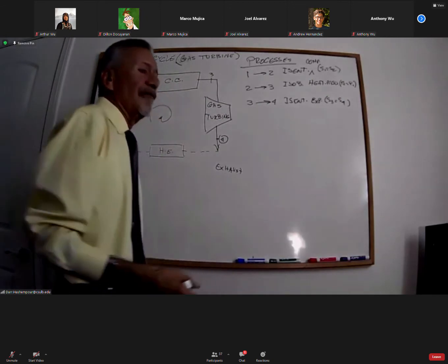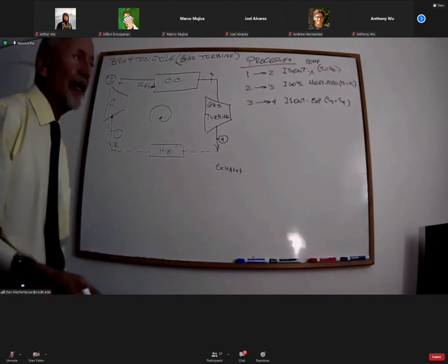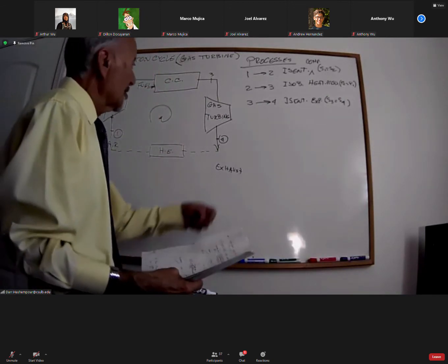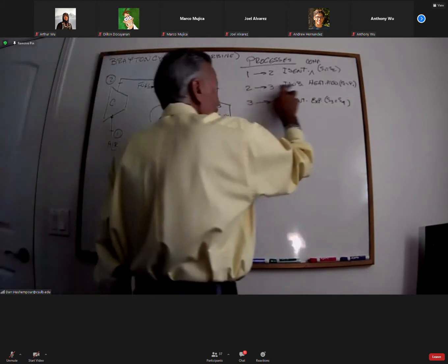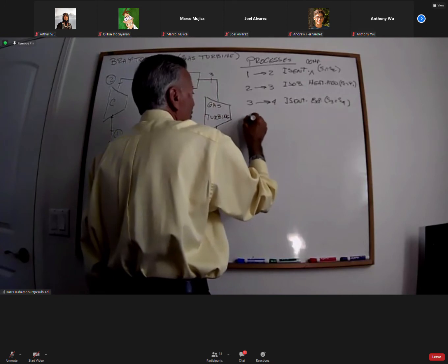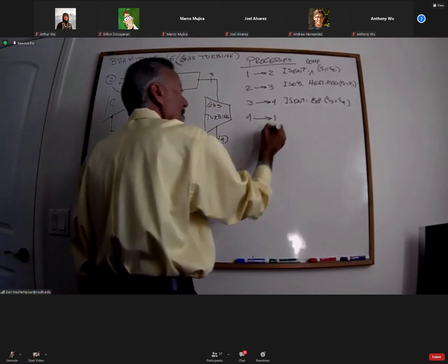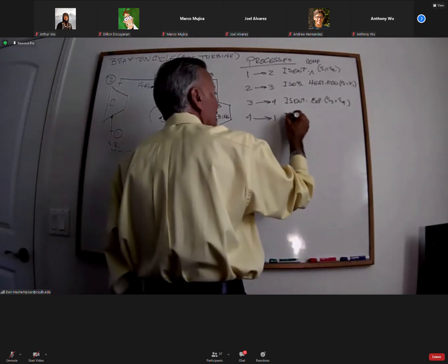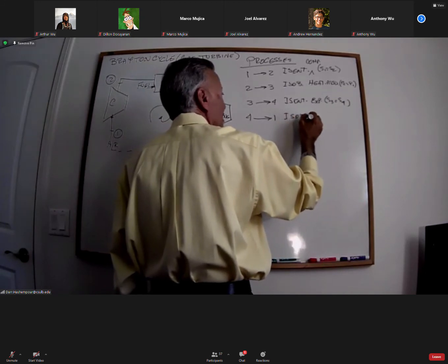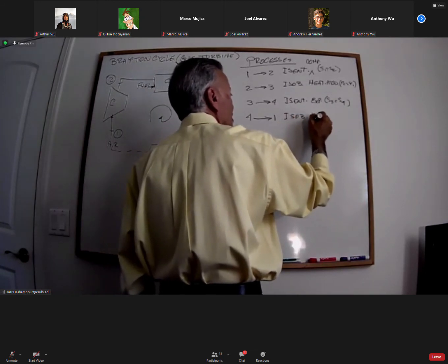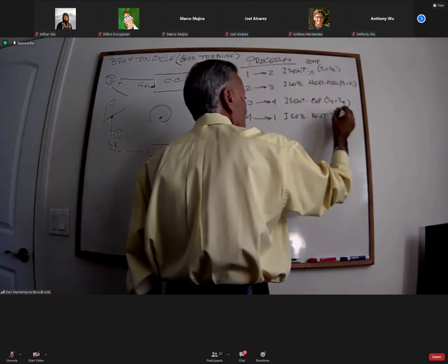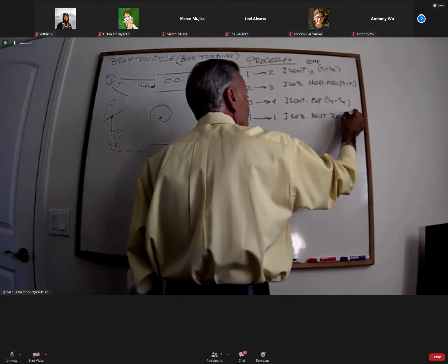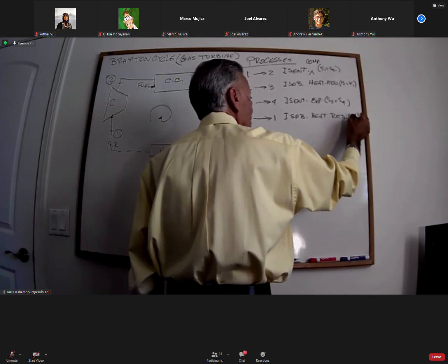Processes 1 to 2 and 3 to 4 never change. The only processes you can change are 2 to 3 and 4 to 1. So 2 to 3 is isobaric. Now 4 going back to 1, once again, is isobaric heat rejection, meaning P4 is equal to P1.